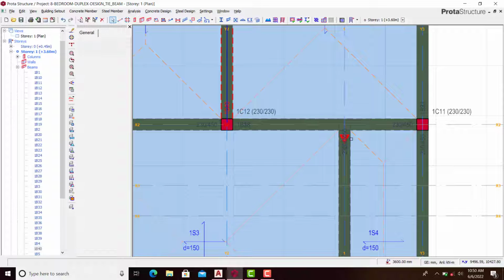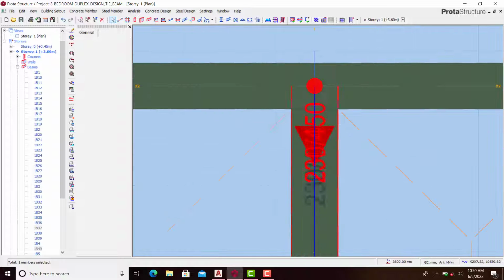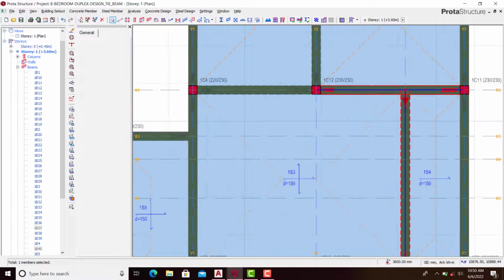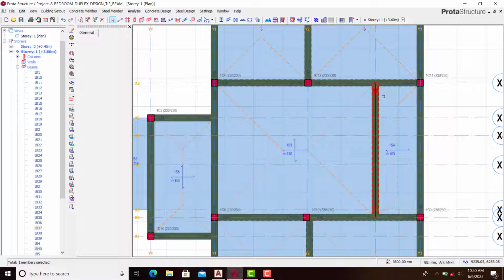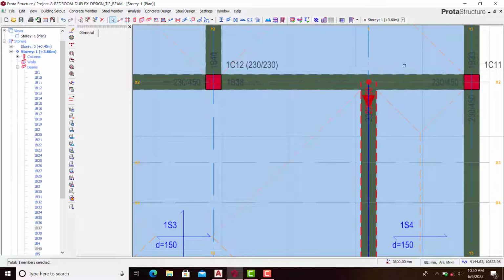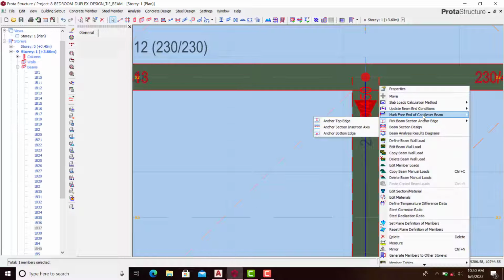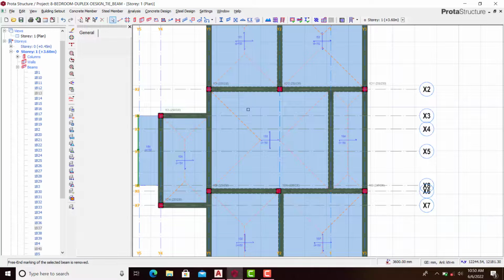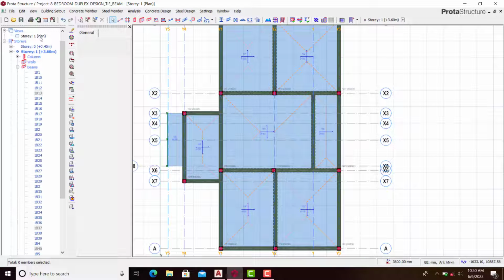Then we can now click on this to remove this cantilever, as you can see, because we inserted this one first. We are meant to insert this beam first, so that we can now insert this beam to carry and tie itself on this beam. So we will now click on this beam to remove this cantilever. We'll just go here and then say supported. So if we go to our 3D view right now, you can see that we have successfully created our